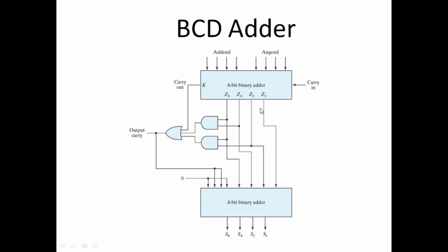The output of the first 4-bit binary adder is given as input to the first binary number of the second adder, and for the second number, the middle two input pins are connected with C, and the first and last pins are connected with 0.